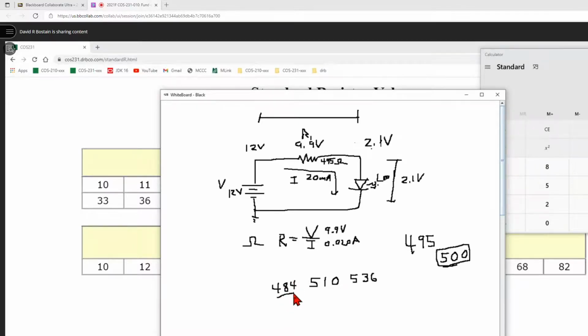Now we're going to check these two values for current, and then we're going to pay attention to this one for power. Because of the formula, a smaller resistor means that the wattage will be higher because more current will be passing. We need to know here also, this is the maximum current. We have to make sure that doesn't exceed 25 milliamps. So let's do those two things.